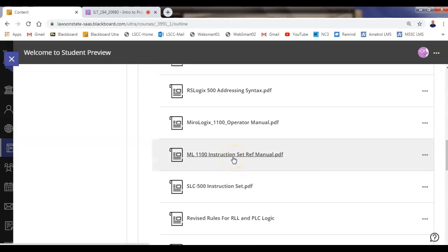This is the PLC. We have 2 programmable controllers that we use in this class. We have a newer MicroLogix 1100, which fortunately it looks like we are going to have enough of these for everybody to move to those. These are what I refer to as hybrid PLCs, and we'll look at that. They're expandable. The other PLC that we have for this class is the MicroLogix 1000. The MicroLogix 1000 is what we call a fixed PLC, which means it's not expandable. This would be the difference between a laptop or a tablet computer and a desktop computer. With a desktop computer, you have the ability to upgrade it and change the memory and do what you want to, but a tablet you can't do anything with. Whatever tablet you buy, that's what you end up with. So we'll look at those in the different categories of PLCs.